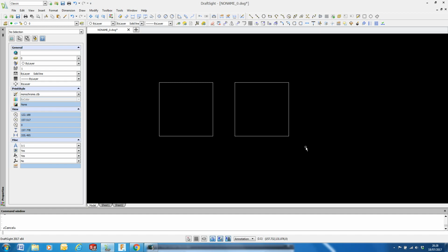So there's a multitude of ways of drawing shapes in AutoCAD or Draftsight, as this is. Either counting spaces on the grid as our previous video, using the absolute coordinates, not very helpful really, using relative coordinates, yeah, pretty helpful, and I tend to use relative coordinates a bit, using e-tracking and just typing in lengths, really useful.